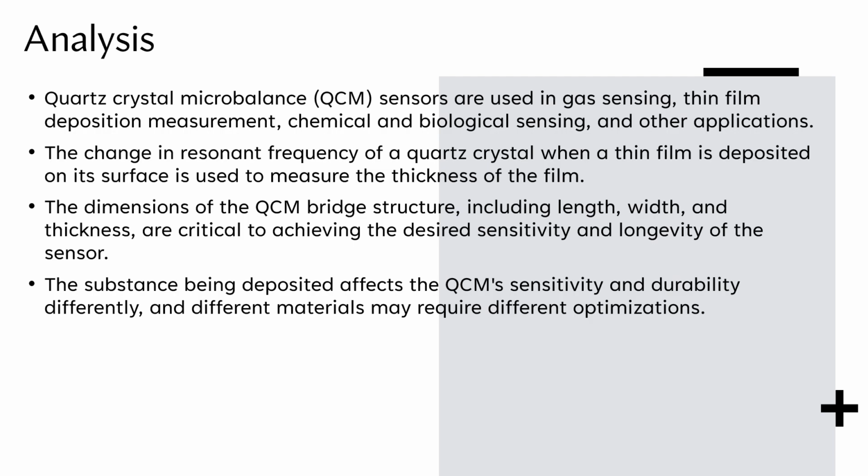The problem of optimizing a quartz crystal microbalance to maximize its sensitivity can be achieved by reducing the number of variables and identifying optimization through relative thickness ratio between the quartz and titanium layers. This can be determined using the stiffness matrix for quartz, the Young's modulus in the X direction, and the Young's modulus of titanium. By plotting the relative curvature against the ratio of thickness, the maximum curvature and thickness ratio can be found.